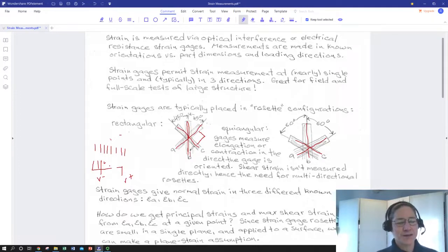You can also notice that B, being at 45 degrees to either A or C, is going to be 90 degrees from either A or C on the Mohr circle. And in fact, let me erase a little here. It's going to have a particular clockwise or counterclockwise direction versus A or C. So if we look at B, it's actually 45 degrees counterclockwise from A, because if you go around in this direction, you're going counterclockwise.